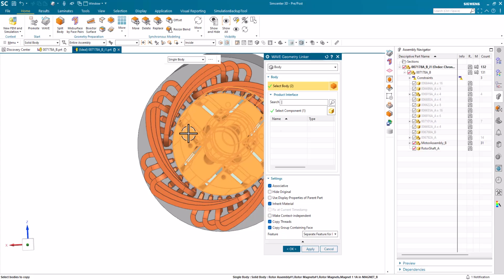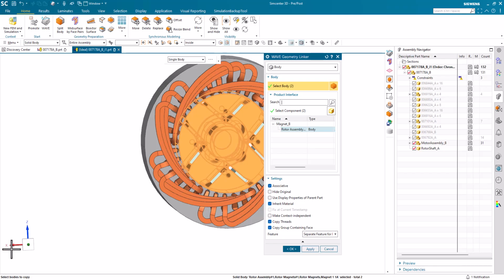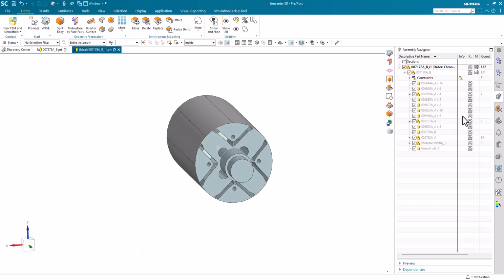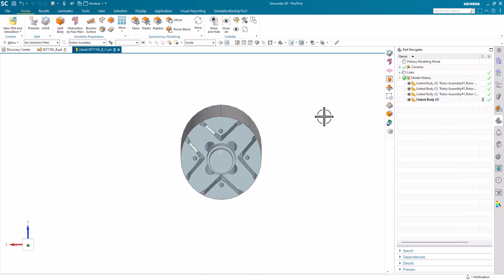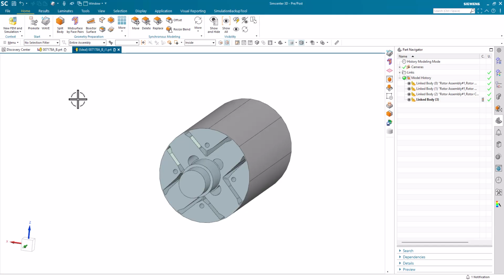So I'm going to produce a sector model, a 90-degree sector model in the positive XZ plane. Go ahead and say OK here. I can hide my assembly, and then this is going to be the solid bodies that I'm going to start working with. So now I'm just going to create some datum planes in order to get my sector and planar face of interest for my plane strain meshes.